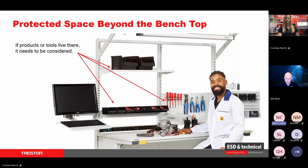The whole goal is not just to ground one surface. The goal is to design the whole work area so the product has a proper place to be throughout the workflow. Yeah, that's right. So a little bit like what we talked about in the last slide, we want to eliminate that decision-making process from the operator, right? We don't want to allow them to have to decide what is ESD protective, what is not ESD protective, and where things are going. So when we tie everything together here, that eliminates that concern that we have.